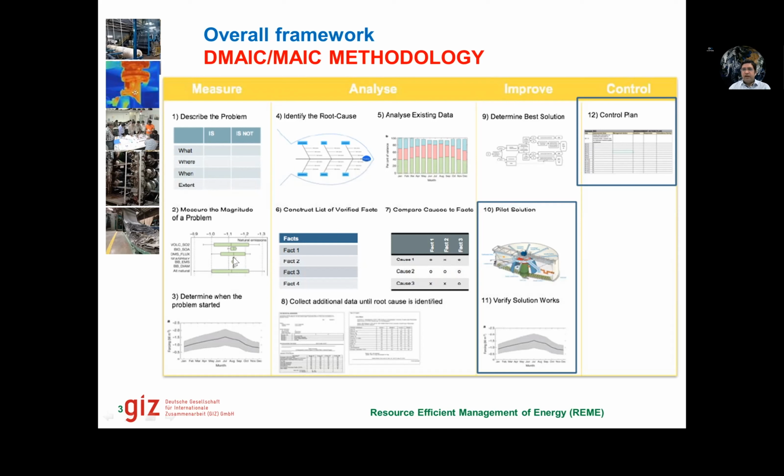So here we need to define the quantity. Is this leakage amounting to 1 ton per hour or half a ton of steam per hour? So what is the actual amount here? Then we determine when the problem actually started. This we can determine if we have a monitoring framework. So we look at our previous reports of leakage assessment or previous reports of steam balance, for example, where we can see that there is a meter on the main header through which all the steam is going. Let's imagine that 10 tons per hour of steam is going through the main meter.